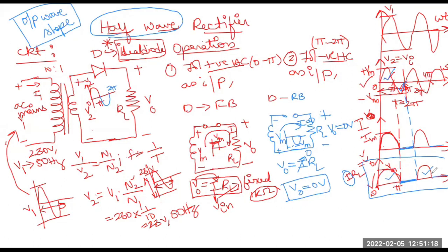Now here I got positive half. For example, I want to have only the negative half cycle in my rectifier operation. So what should be the circuit change? Diode reverse. The diode should be reverse connected. So if this diode is reversed, you get an output which is like this. So what do I see? No positive half cycle, only the negative half, like this, when the diode in the circuit is reversed like this. Okay, so this is how you have the operation of a half wave rectifier.